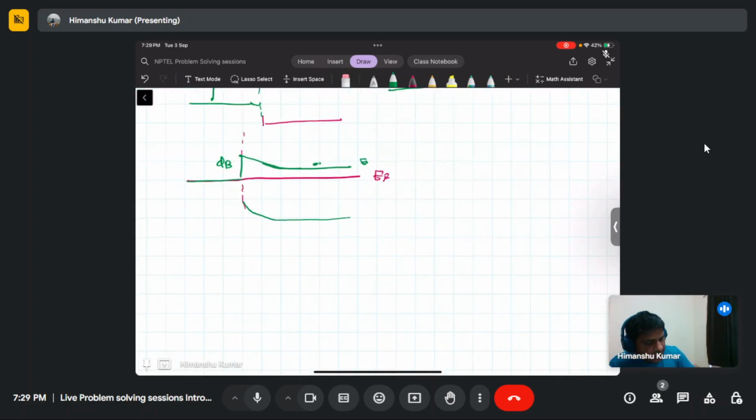In the other direction, holes will take part in the conduction, and they will recombine with the electrons in the metal, and the conduction will take place on the other side of the junction. Or if you pull this barrier down, then this barrier will get reduced, and you will see a flow of current in the Schottky barrier junction. And still you will see some threshold after which it starts conducting, and that is known as the Schottky barrier threshold.